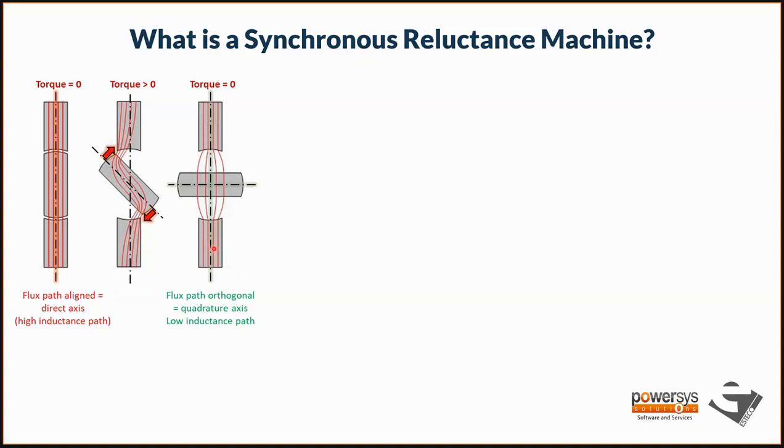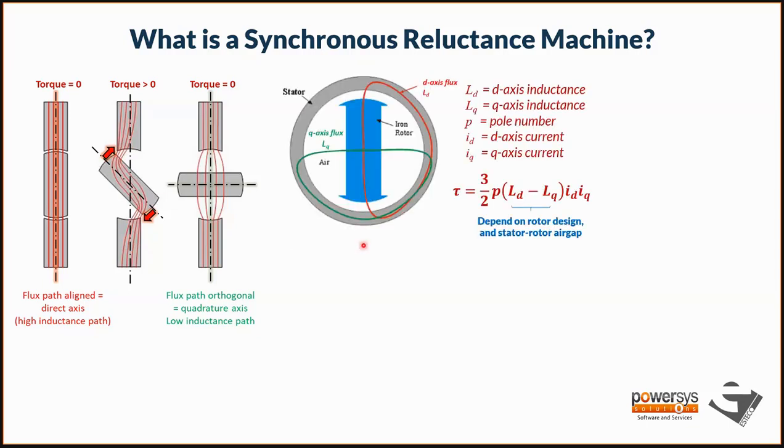That's because the flux path is symmetric and the reluctance doesn't really play a role. But anywhere in between, when it's not aligned, the reluctance variation with the air and this magnetic material will develop torque, which will try to push this rotor piece to align with the stator pieces. So this one is shown in a linear fashion. We can also convert that onto a more circular or cylindrical portion, which depicts an electric machine.